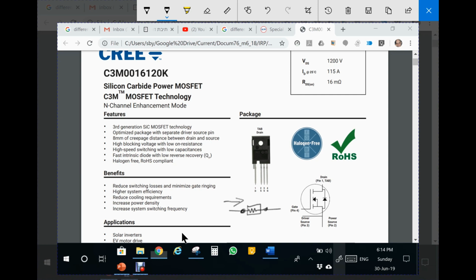The current passing here, there is a voltage drop on the device, and you'd like to find out what this voltage is. Now one way to do it would be just to take a wire here and a wire here and measure the voltage. If you do that, then you have a problem that there is a voltage drop in this connection here, which you actually see as you measure it this way.